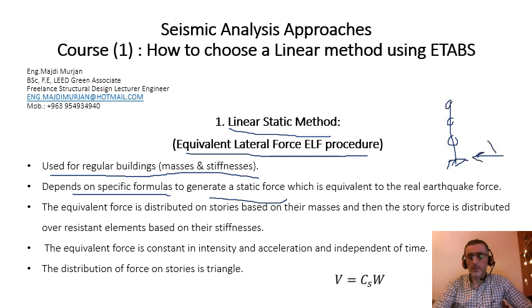This is the earthquake, and here every floor will resist like this, and this distribution on floors will be a triangle. So every story will get some share of this shear force, and then it will be distributed to the resisting elements based on their stiffnesses.